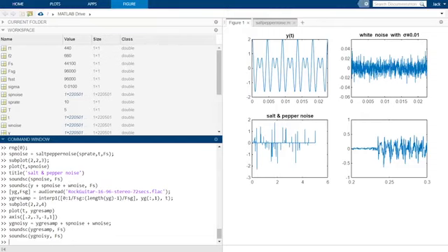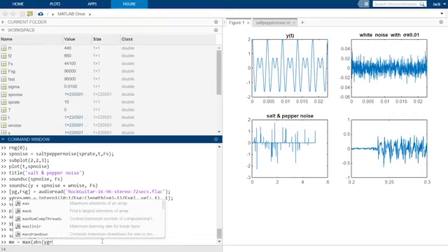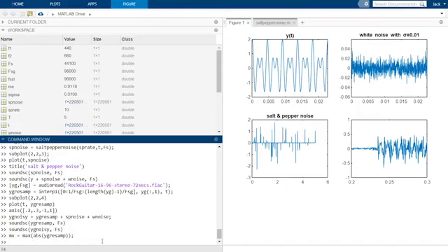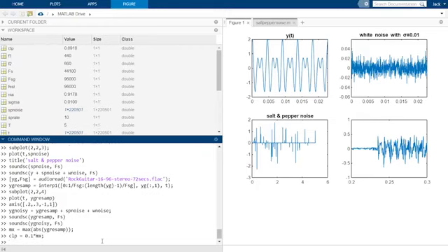We can easily simulate this in MATLAB. First, let's find the maximum magnitude of our clean guitar signal as max. To distort this signal, we will clip it to a maximum magnitude equal to 10% of the max value in the signal. We initialize the distortion signal to be equal to the clean signal.